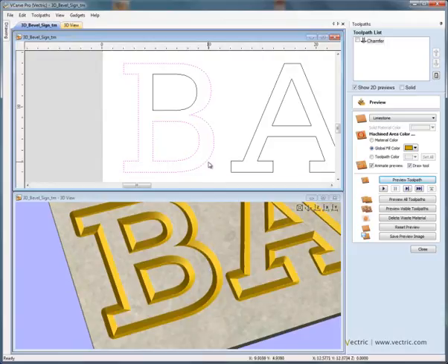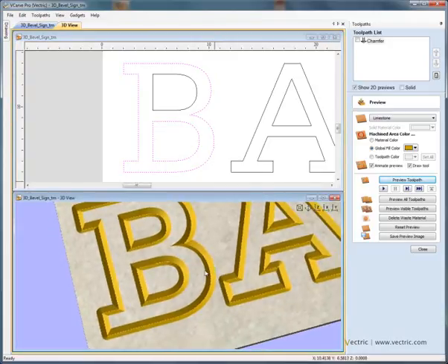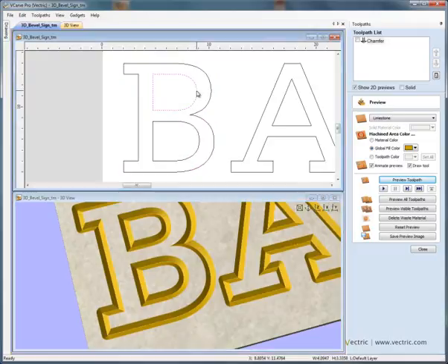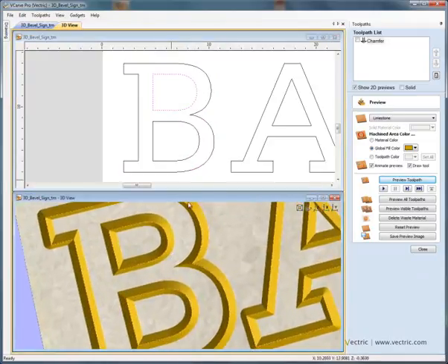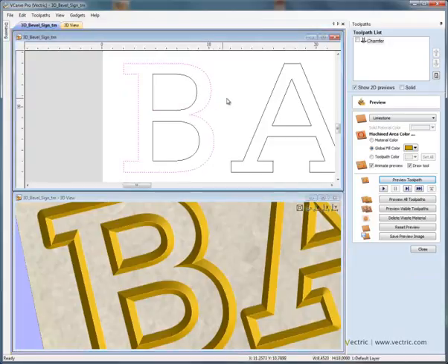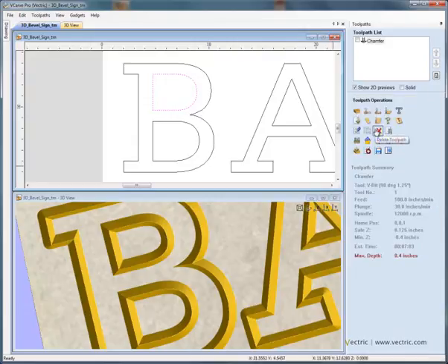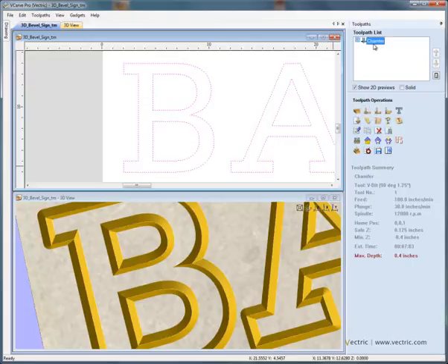The chamfer is being extended outside of the size of the letter. So we're chamfering to make the letter larger on the outer edge, also on the inner edge. On the inner edge of the letter B, the software is offsetting on the inside and on the outside. So it's retaining this flat portion to be the same size as is defined by the font, then it's adding the chamfer.